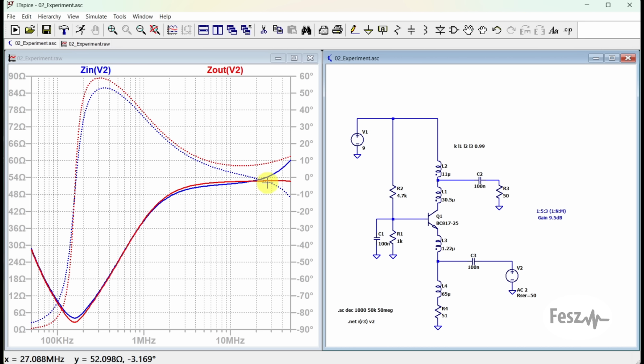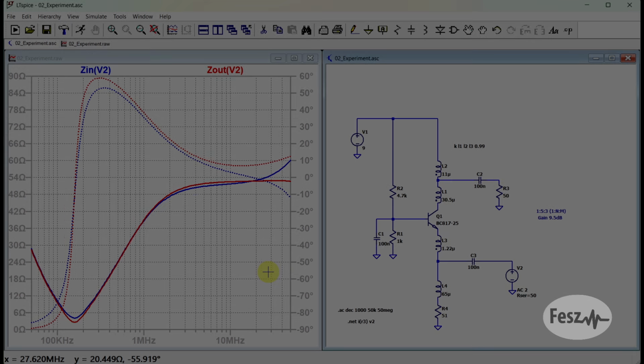Before and after, we are getting various nonlinearities because of the exact inductance values, but also because of the non-ideal transformer couplings. So with the connected source and load impedance, the amplifier is matched on both ends, at least in the linear range. Therefore, in the simulator at least, the circuit is working as expected.